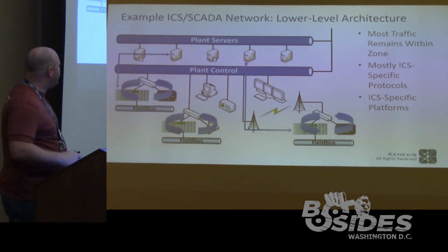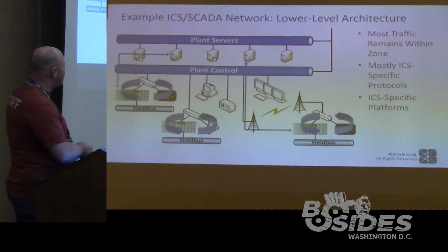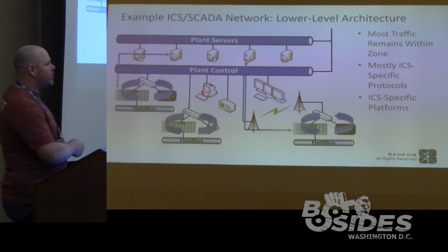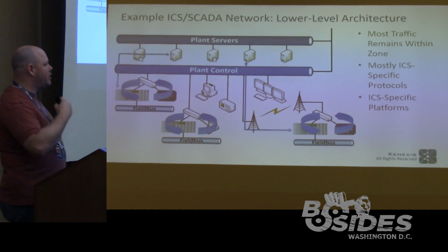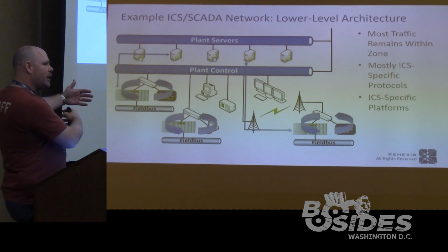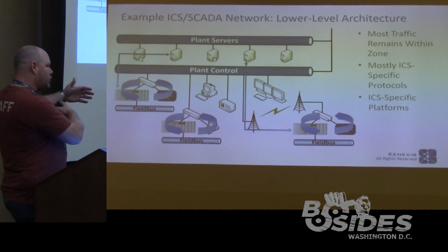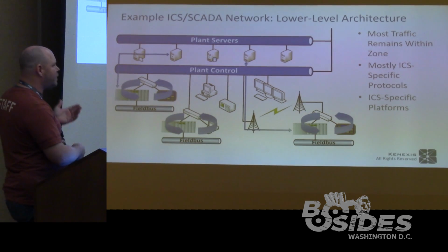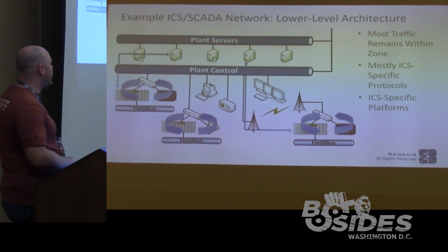But the majority of all that traffic resides and stays in these small remote sensors. You may have, say, an engineering workstation that can talk to these over the network, but it isn't constantly communicating. This is when they need to make a change, they go out, communicate with that controller, and they do a particular task, and then they log off, because you don't want to leave that session up and running, especially if these are low bandwidth links that are running over radio or satellite, things like that.